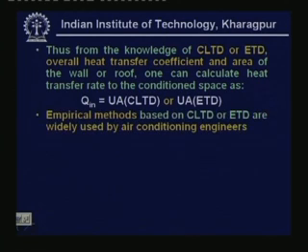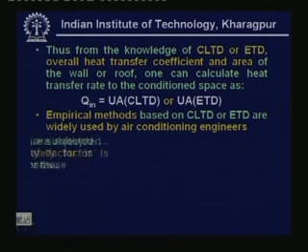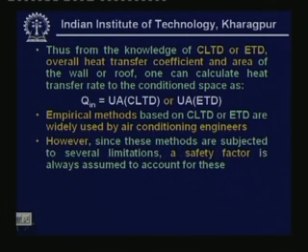Okay. Now the empirical methods based on CLTD or ETD are widely used by air conditioning engineers. However, since these methods are subject to several limitations, a safety factor is always assumed to account for these. Okay, so they are not 100% accurate, all these empirical methods. So to take care of this, a safety factor is always assumed.